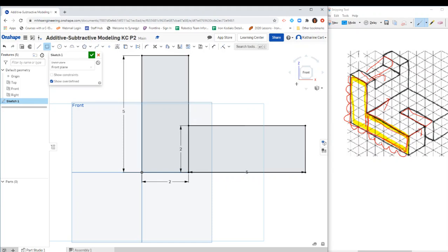Now I'm going to hit the front to zoom it out. Now I can go ahead and I'm going to use this neat tool. You don't have to use this. I can hit finish sketch and go to extrude right away. But if you want to, you can use this tool called trim. And really in our drawing, we don't have this line right here. So watch what happens. I just trimmed it and it went away. I clicked on this trim tool, clicked on the line, and it just erased it. And what's good is that it's still gray, and that's indicating that it's still a closed shape.